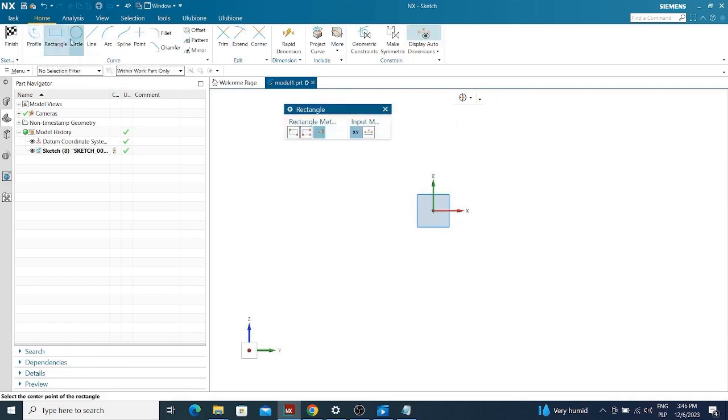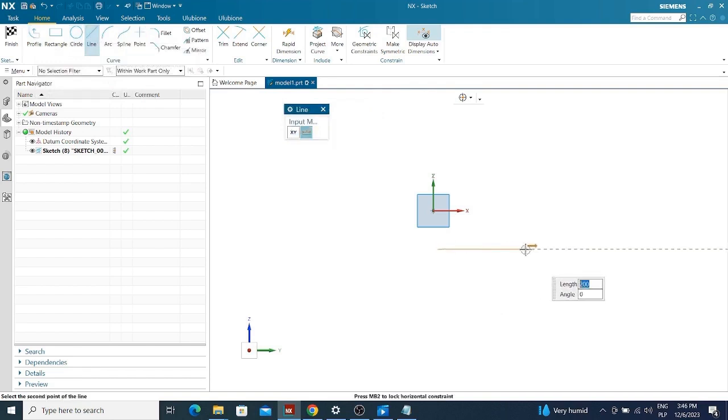Besides standard tools like rectangle and circle, there is a very cool tool that I often use. This is essentially the profile tool. It is also located under the Z key on the keyboard. And maybe to demonstrate the difference, I'll first use the line tool, which is just a simple line, to show the basic functionality of this tool. And here, if after drawing one line I want to draw another, I have to click on the endpoint again, possibly select it, and do this every time.